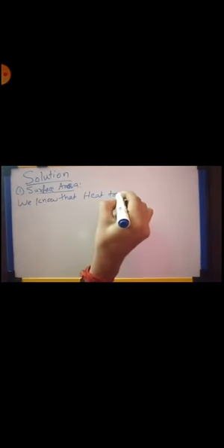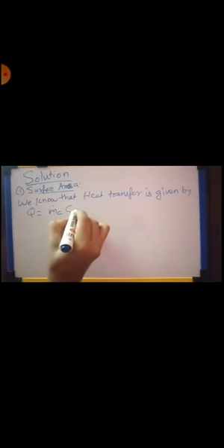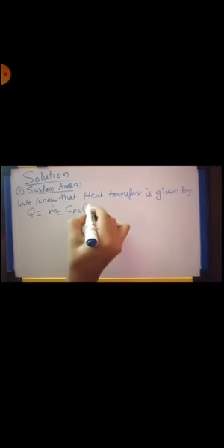The next step is to find out the heat transfer Q. We know that heat transfer Q is equal to m dot c, Cpc into T2 minus T1. We consider the cold fluid. The m dot c is given as 1000 kilogram per hour, which is converted to kilogram per second.